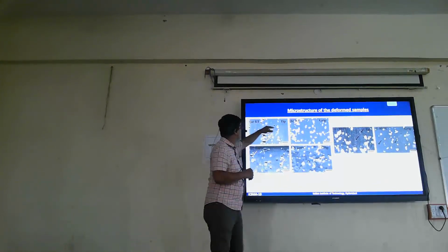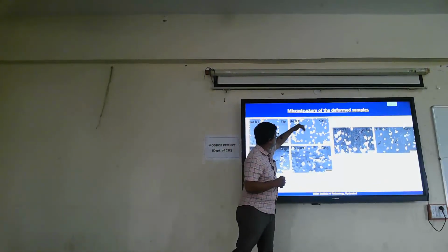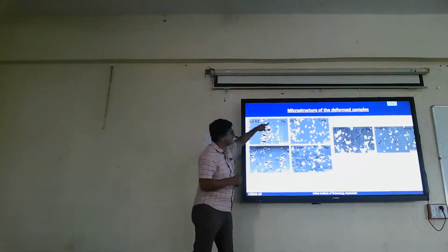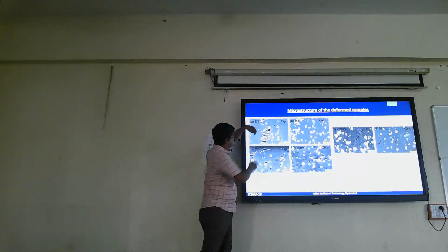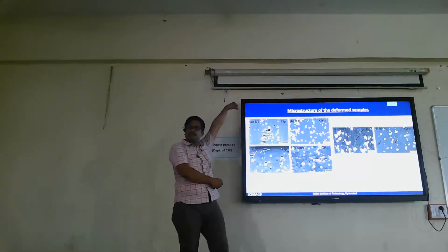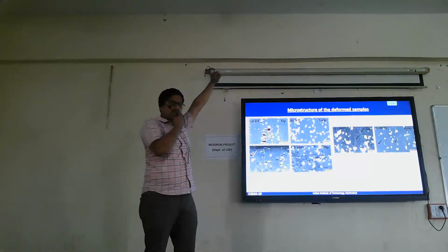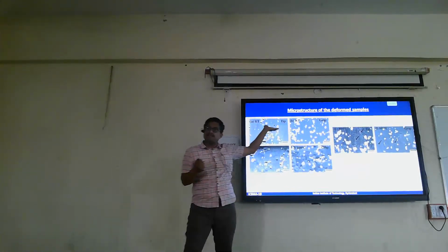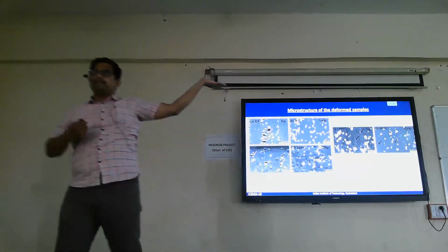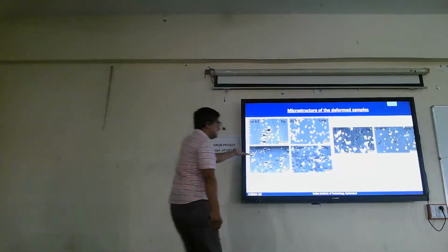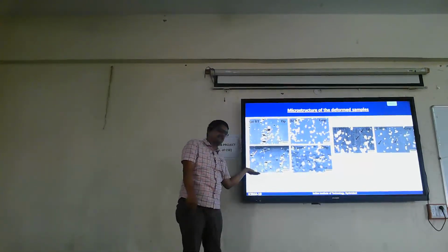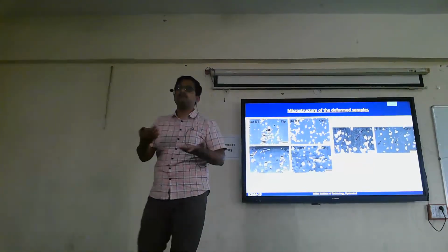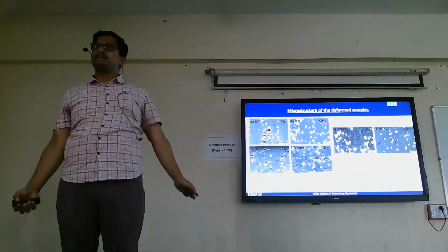This is a sigma phase. This is the tip. In the tip portion, you're not seeing fracture of this sigma phase. In the grip portion, where the deformation is taking place, my sigma phase is fractured perpendicular to the tensile axis. Definitely it is because of cracking. But this is there at 200 also, room temperature also, where I did not see serrations. So even at 600 I can't say that this is the reason for the serrations. At 200 I am also seeing a significant number of cracks where I did not see serrations. That means this is not actually responsible for the serrations.